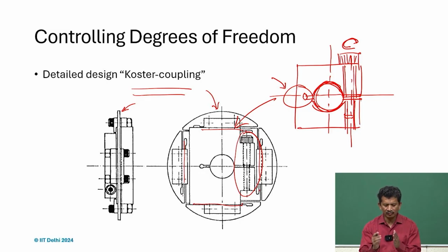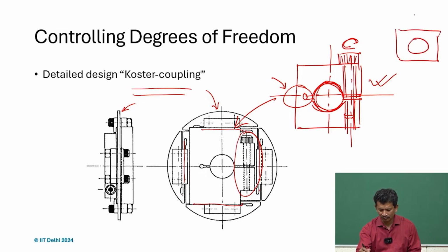So, that way you do not damage it. Always remember, this is one of the design elements we should remember. We should never do this kind of thing. Many times we just drill a hole, tap a hole, and then try to lock it, but it damages the surface and it is not reusable.